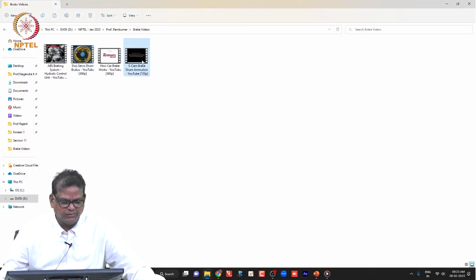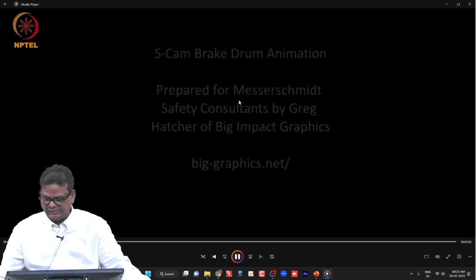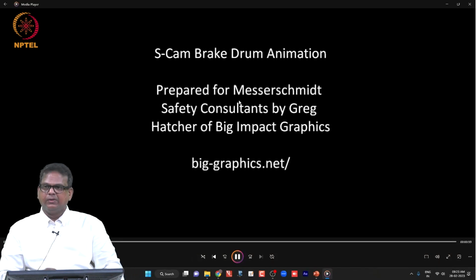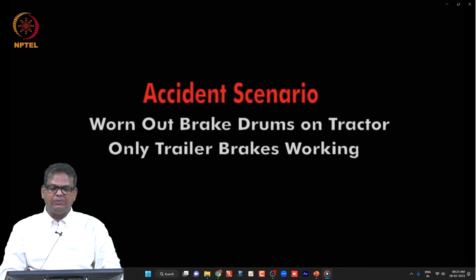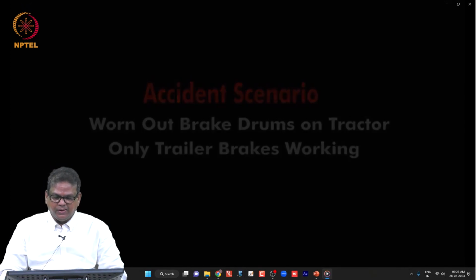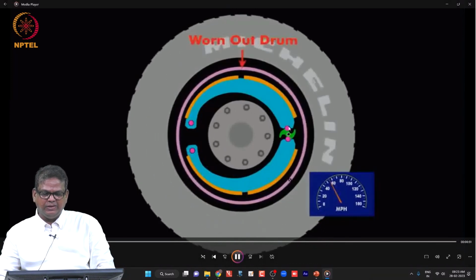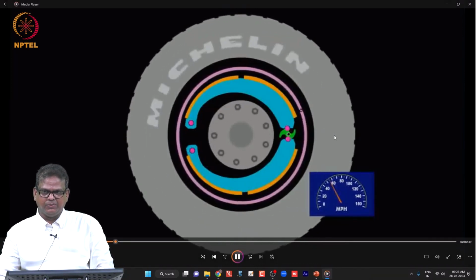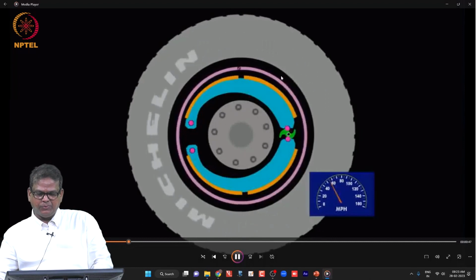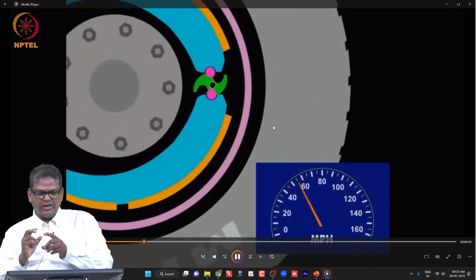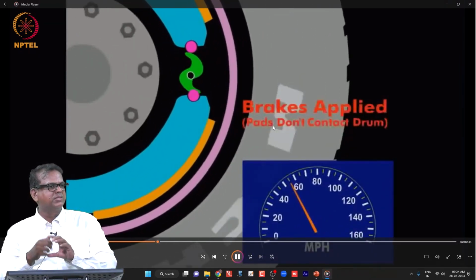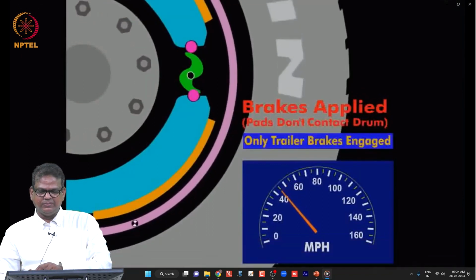There is one more, when you have heavy vehicles, where you talk about the trucks and buses, where you need to have an air brake system. There you need to have a smooth transition. So instead of a wheel cylinder, you have an S-cam type. When the brake fluid approaches here, the cam will rotate equally on both sides. You can see that.